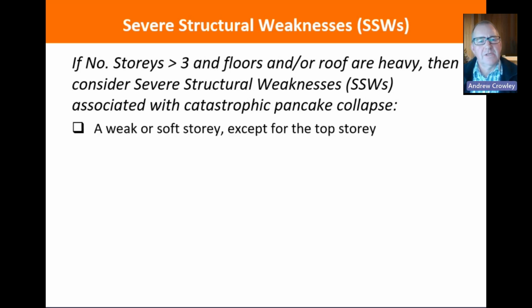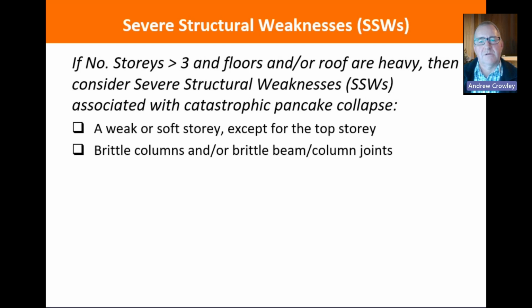So, as mentioned, a weak or soft story. This is a common cause of failure in commercial multi-story buildings, that the lowest story, although it's the heaviest loaded, is often the weakest, particularly to lateral load. Have you got brittle columns and brittle column connections?